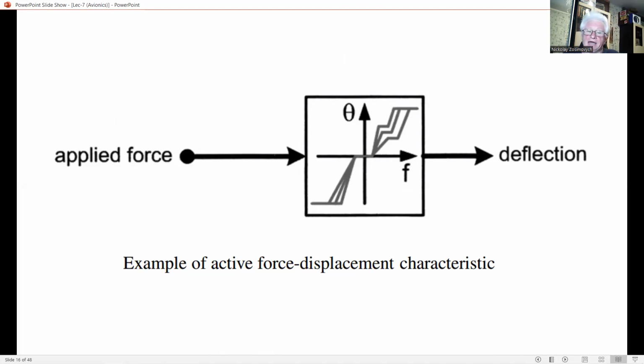Soft stops are intermediate force thresholds to bound the zone of carefree handling, while the variable gradient provides the desired feel characteristics over the flight envelope. Provision of such characteristics in a passive inceptor would be impractical because of the mechanical complexity involved.